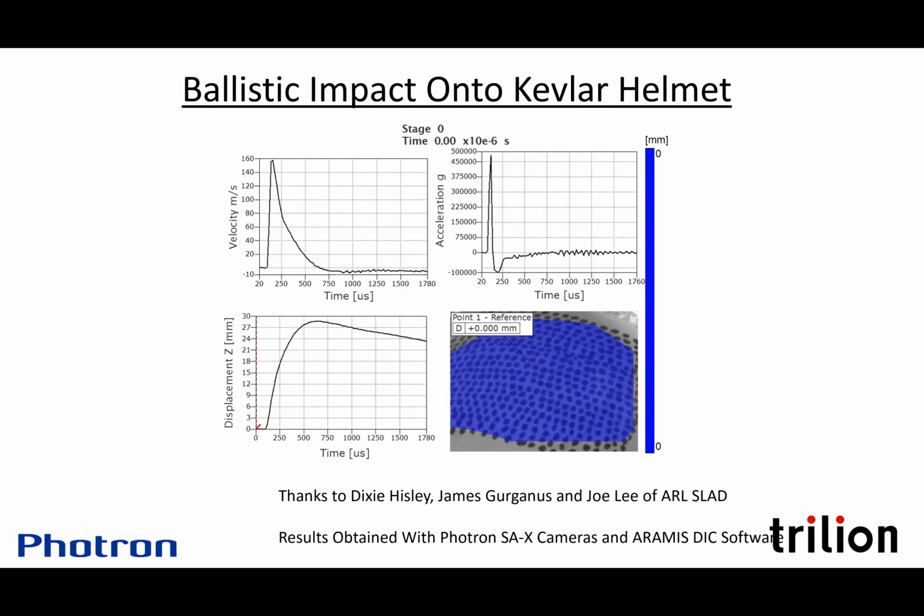We're using the camera clock to drive the data logger, and you have oversampling capability. You can tell it to log one signal per camera frame, or you can oversample by, let's say, a factor of 20, and you can see the analog value between the high-speed camera frames if that would be useful. So again, the short answer is absolutely yes, and it's built in and easy to do, easy to go set the scaling and convert from volts to force or whatever is appropriate.